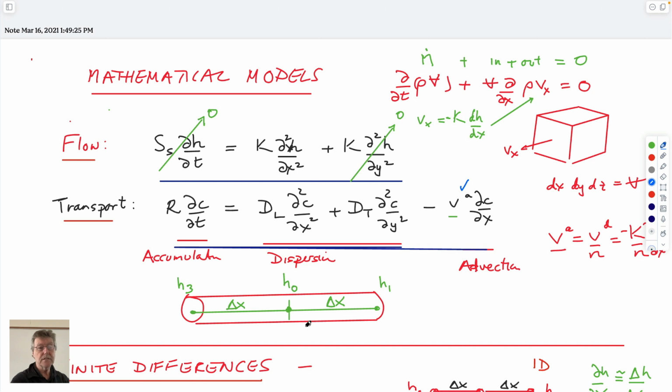They may work with things like reaction and retardation, so you might have multiple solute components, just like you're doing with your assignment number 7, where you have 3 components that are dissolved in groundwater and would be traveling with different velocities because of retardation downrange and with different relative concentrations downrange from their starting concentrations. But you can do quite complex things.